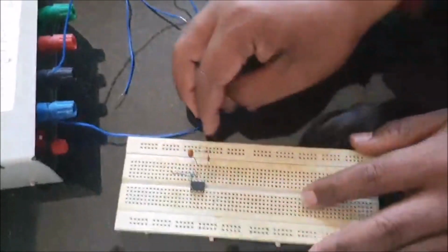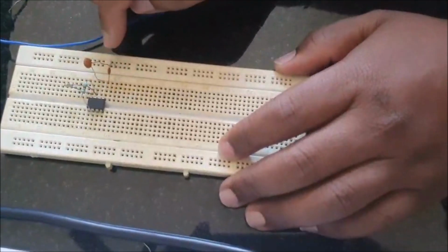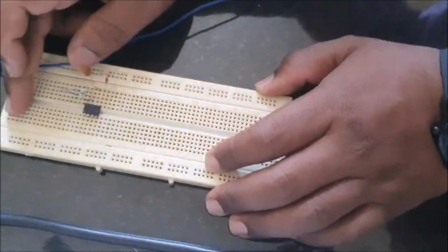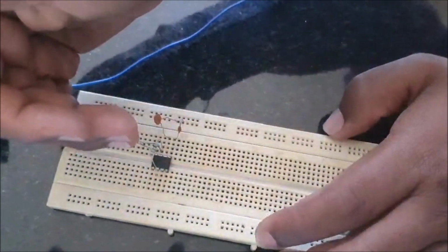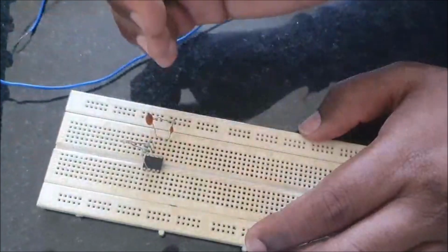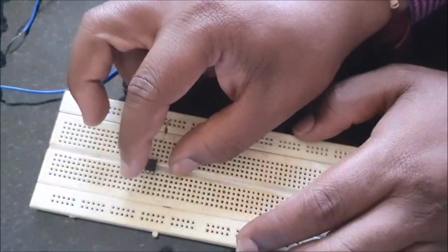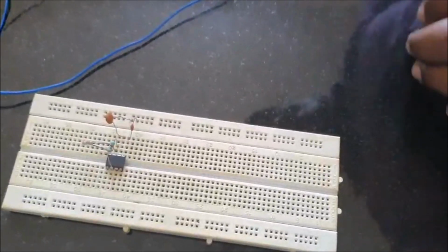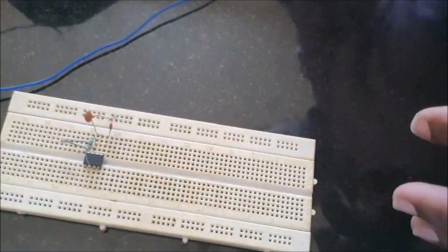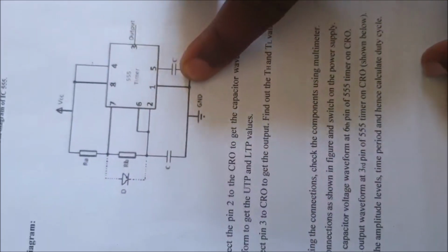See here, this is a parallel connection, that's why I am connecting the pins one below the other. These two columns, that is column 2 and 3, are in series connection, so I need to consider the pins one after the other. See here, this is how we need to connect the two resistors as well as the two capacitors. And from the circuit diagram you can see that pin number 1 is grounded.